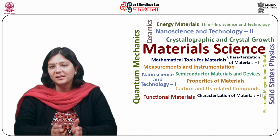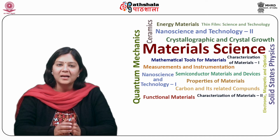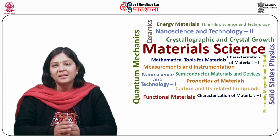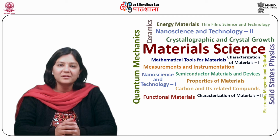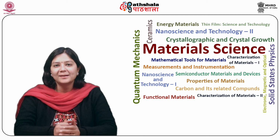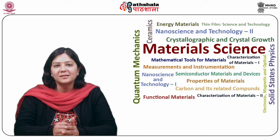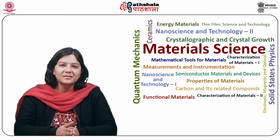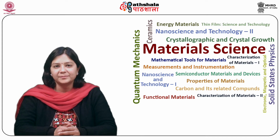Additionally, a new material can also be deposited in the desired pattern under the photoresist. This technique is widely used in semiconductor industries to produce modern CMOS devices. Fundamentally, photolithography is somewhat similar to conventional photography in the fact that the patterns or features in the resist are produced by exposing light onto it.